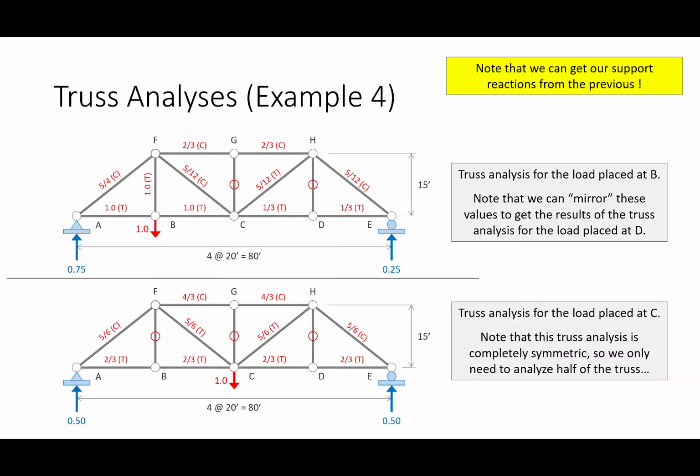All right, hold on. Eyes up here. Let's focus. Does everybody agree that this is the complete result of the truss analysis when the load is at B? Okay, everybody agree with that? Now, this is what I'm proposing. I'm imagining printing this out on a sheet of paper and then taking the sheet of paper and flipping it over. What number am I going to see right here? Oh, 1/3. There we go. I'm going to see +1/3. Does everybody else see that? Everybody good? Okay.